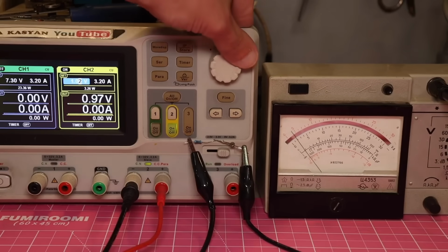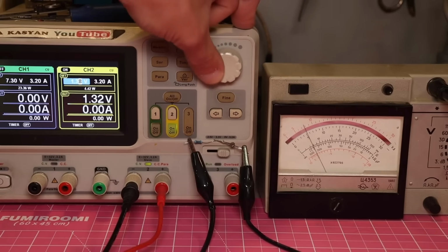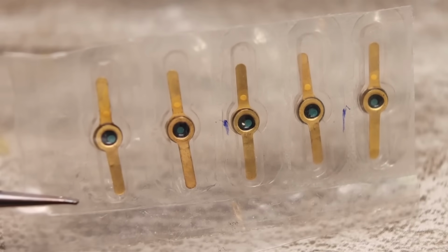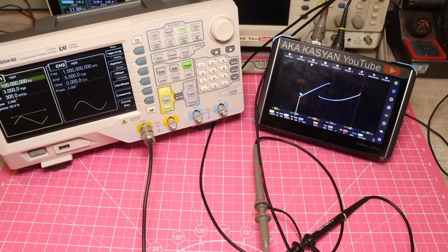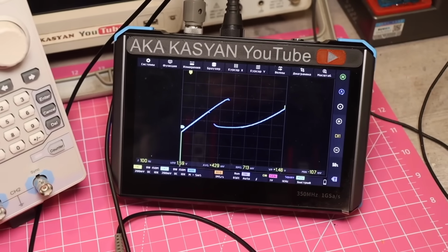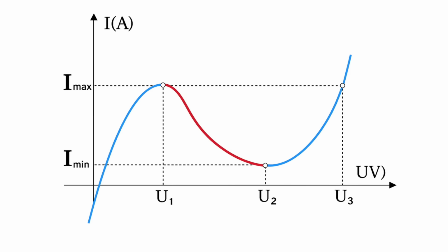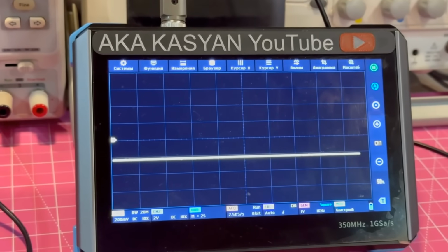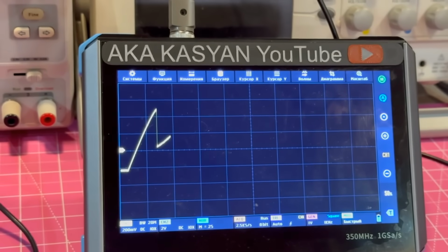The voltage is increased even further, the regular carrier injection mechanism kicks in, and the current will start to increase naturally. That is, on the current voltage characteristic of a tunnel diode, there is a certain section that's commonly referred to as the region of negative differential resistance. It's called that because the current voltage characteristic has a negative slope in this region. This section appears when tunneling, which provides current at low voltages, begins to weaken.